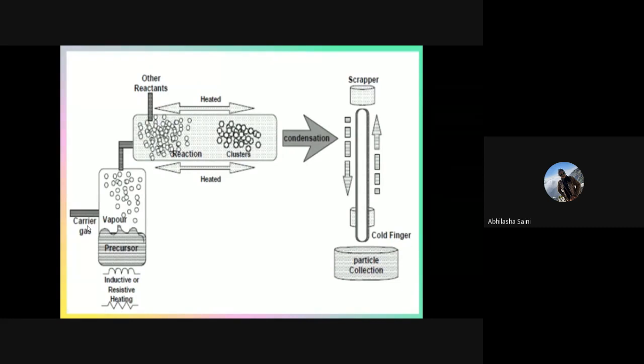Okay guys, the inert gases do not react, they have no reactivity, so they do not react with other chemical materials. So the carrier gas will be chosen from such inert gases, which cannot react with these vapors. Their only job is that they just carry these vapors, helping these vapors to flow inside the chamber. So the carrier gas helps these vapors to come to this chamber.